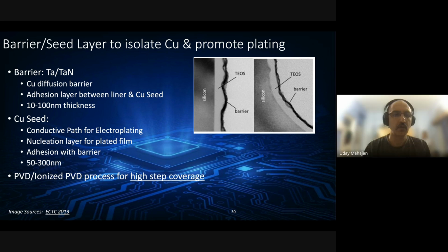So ruthenium is still under development, right? For TSV applications, it's not really taken off yet. So there will be challenges, of course, right? But it gives you better step coverage and better uniformity. I believe the back end of line metal layers in interconnects are already starting to use it to some degree, if I'm not mistaken. So I'm sure there is significant work already done, not at the TSV level, but in back end of line metallization processes to integrate ruthenium.